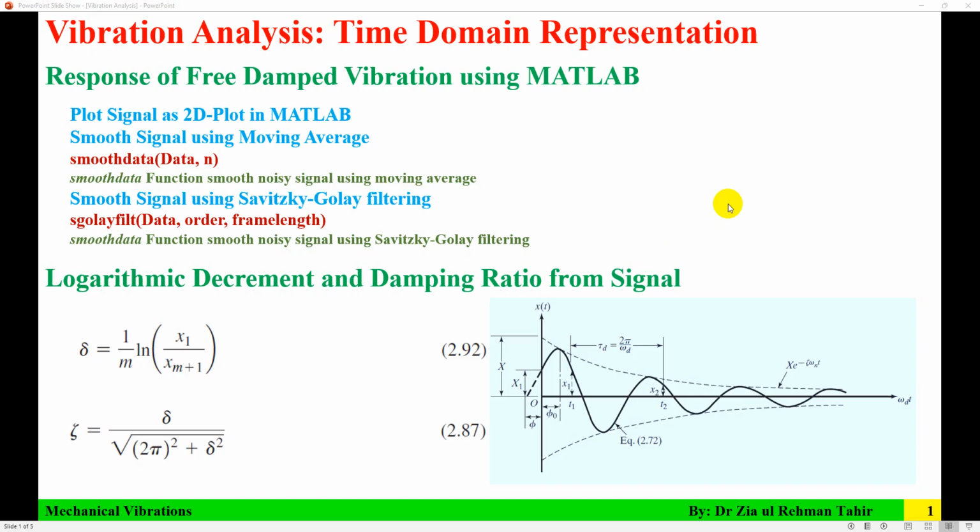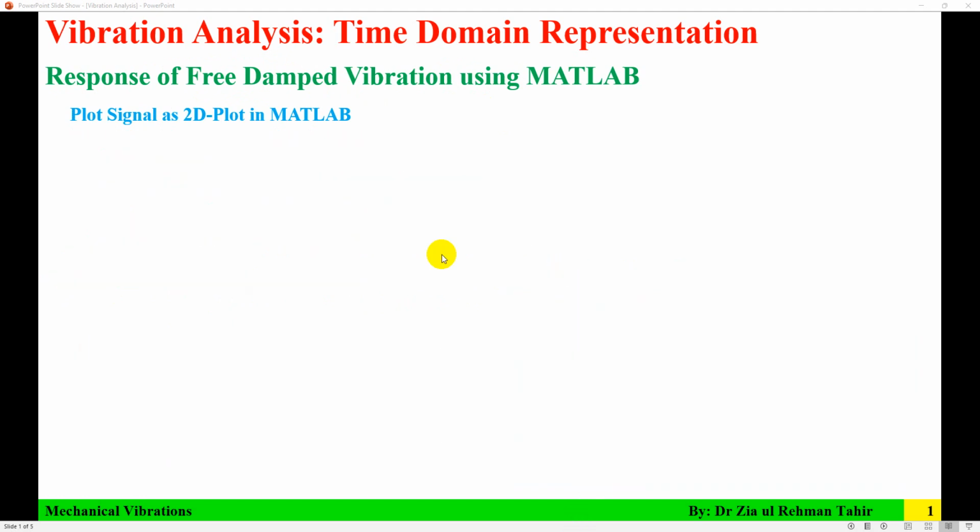This video tutorial is about vibration analysis and time domain representation of a vibration signal. In time domain representation, I'll plot the response of free damped vibration using MATLAB, and then in the second part I'm going to find the logarithmic decrement and damping ratio from the signal. I'm going to plot the signal as a 2D plot in MATLAB.